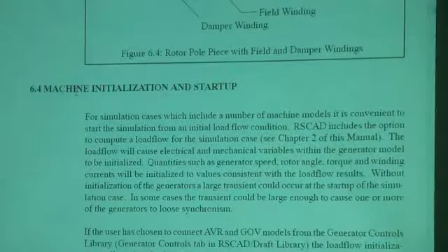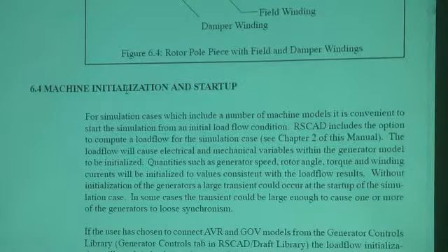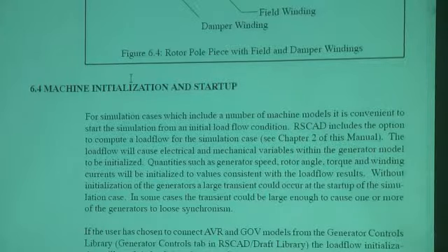Now, the machine initialization and startup. This is part of that load flow. Remember, Cyprian introduced load flow, where it goes through its iterations and back calculates the source voltage.